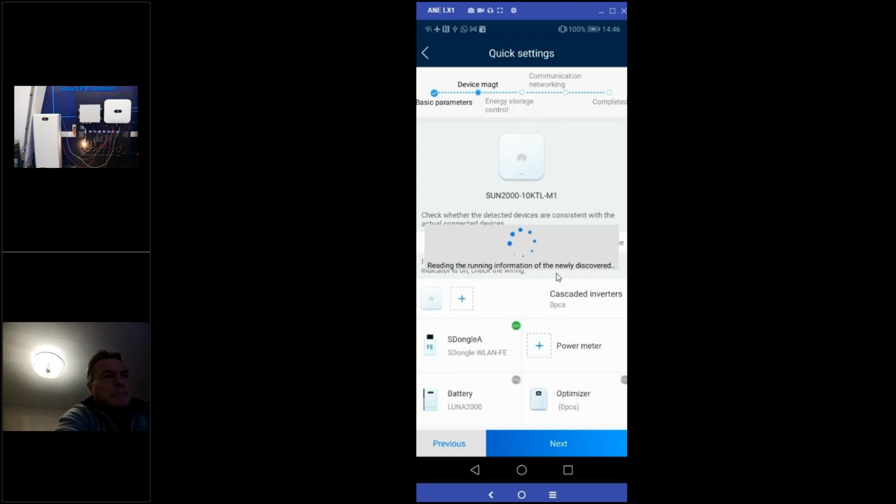So this is very important to remember. And also additional information from my side, from my experience. On the left side of the battery, on the power module, you have the button. This is called black start button. Please do not trigger the battery by this button during the first commissioning. When you do it, you might have little problems after. I mean, the battery might switch off automatically after the working day and will not start up automatically again. If you connect the enable signal properly, the battery should be started by the enable signal by the inverter and nothing else has to be done according to this.